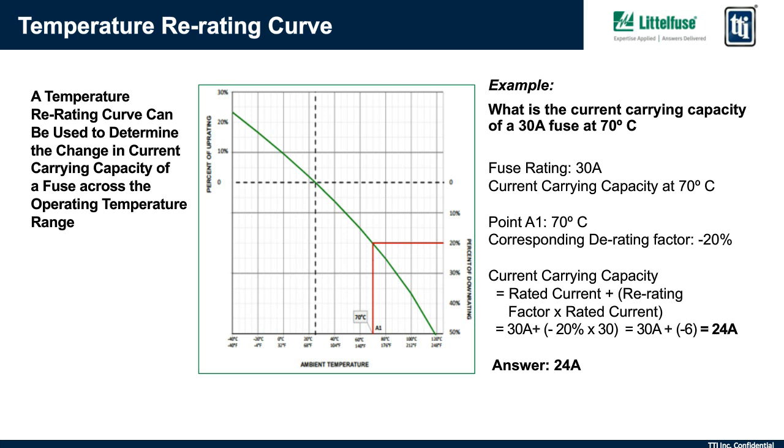If the fuse is mounted in an enclosed fuse holder, then the ambient temperature is considered to be the air temp immediately surrounding the fuse holder, not necessarily the air immediately surrounding the fuse inside the holder.